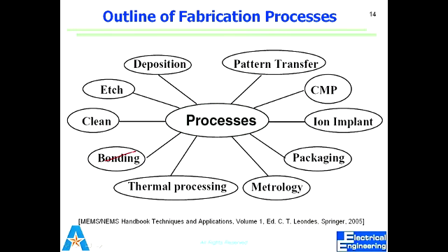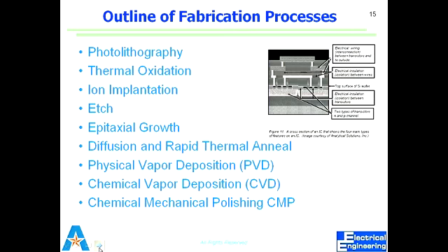Thermal process, of course, we know one thermal process so far. What is that? Oxidation, right? Done at high temperature. We'll see other thermal processes as we go on. So this is essentially a breakdown of what we're going to see. More precisely, these are the technical terminologies. As we progress, these terminologies will become easy because there are specific meanings of certain things, and that's my goal, to make you comfortable with those. So, photolithography: transfer of design using optical wavelengths, right? Within that range. If you go above or below, it becomes a different type of lithography.